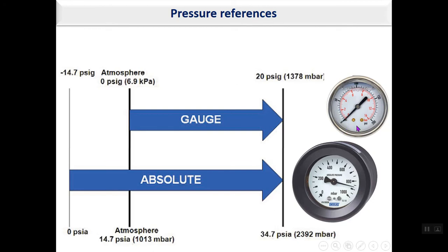Suppose this gauge pressure measurement device is moved from sea level to above a mountain. Does the pointer change its location? No, because it measures the gauge pressure, and gauge pressure is 0 everywhere, either at sea level or above a mountain.